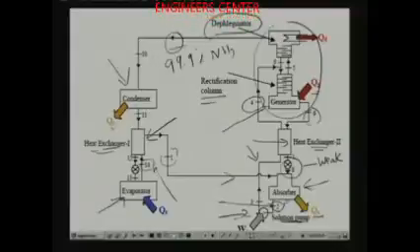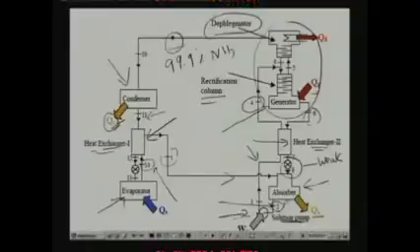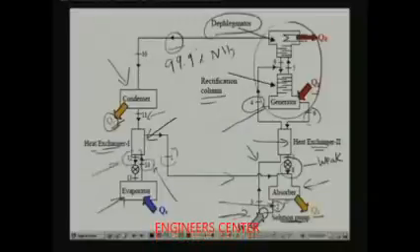It condenses in the condenser by rejecting heat of condensation QC to an external heat sink, and it becomes a high pressure liquid at point 11. The high pressure liquid at point 11 now flows through the heat exchanger, where it rejects heat to the vapor coming from the evaporator. In this process it gets subcooled, so at point 12 you have subcooled refrigerant liquid still at high pressure.